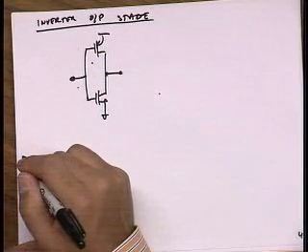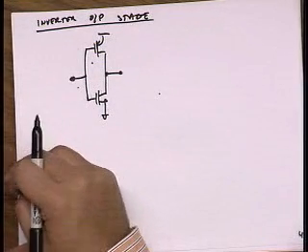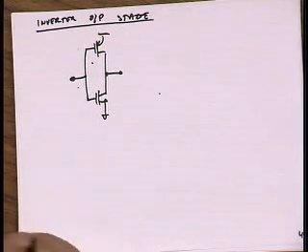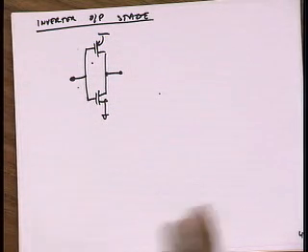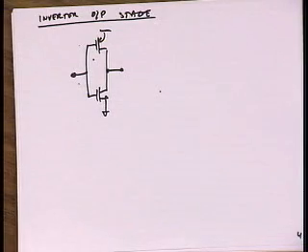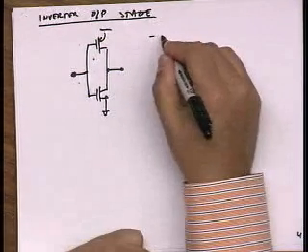So what are some of the issues with this as an output stage? Anybody? Say you want to use this for your project. Let's say I add a bonus to the project: put an output stage and drive a 1 kilo ohm load. Would you use this? Okay, maybe we get somebody else. Just give me one potential issue with this as an output stage. You don't have to give me all the reasons. Just one issue. Yes, Vincent. The DC bias point? Yeah, very good. So how do we bias it?